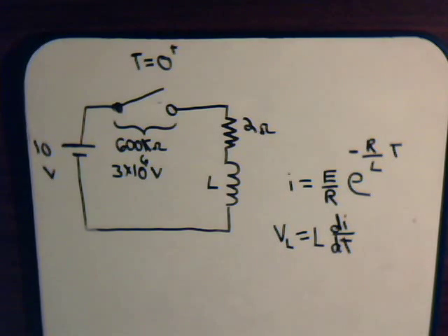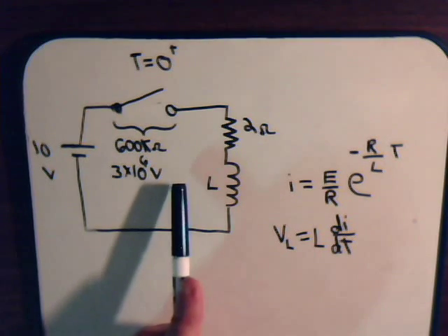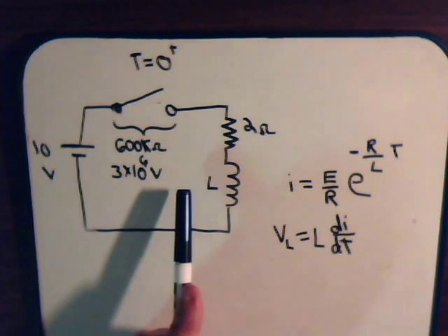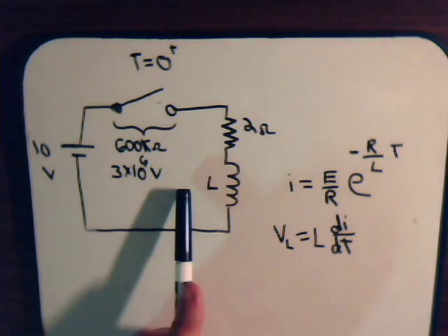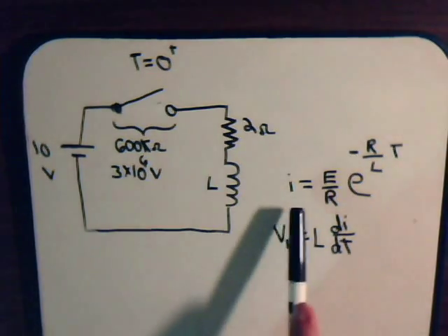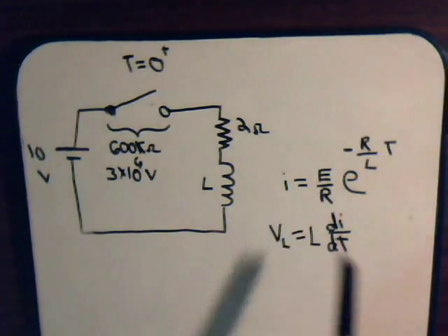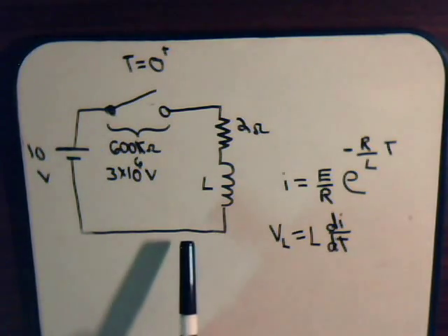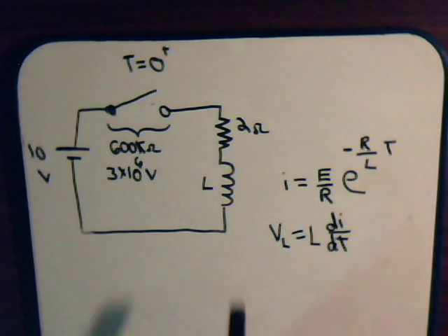So what is done is to include a discharge resistor. What we're going to do is show what the circuit looks like when there is a discharge resistor, and then, for that type of circuit, since we know what the decay current is, determine what the voltage drop across the coil is going to be. We're going to derive an equation for that. So the situation is like this.